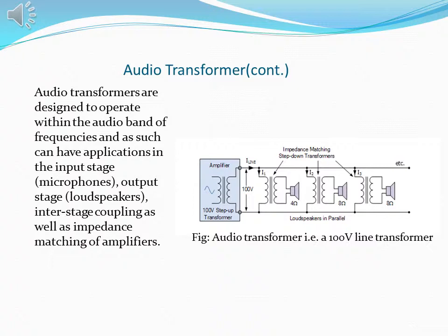These types of ceiling-based speaker systems use multiple loudspeakers located some distance from the power amplifier. Since the impedance of a typical loudspeaker is generally low, an impedance-matching step-down transformer, usually called a line-to-voice coil transformer, is used for each loudspeaker connected to the 100 volt line as shown.